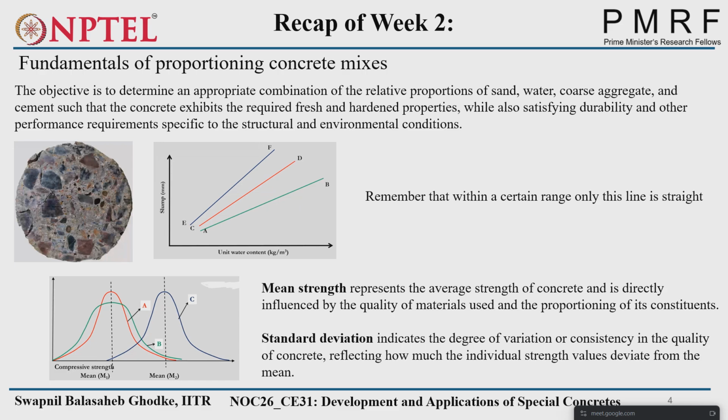Okay. So if the spread is more, is it good, or is the spread less good? If you compare A and B, which one will be the good mix? Spread A will be good because we have the lower standard deviation, meaning we are getting more nearby results, right?